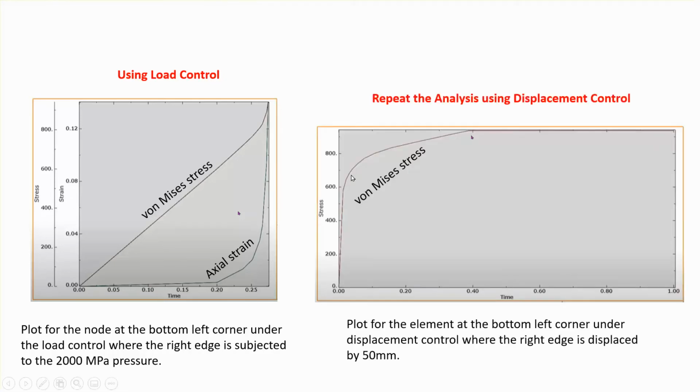We're going to get a curve like that, and you will see that this is the elastic region, this is the plastic region, and at this point, which is the last stress point, basically the program assumes that the stress is constant, and you'll see what's going on.